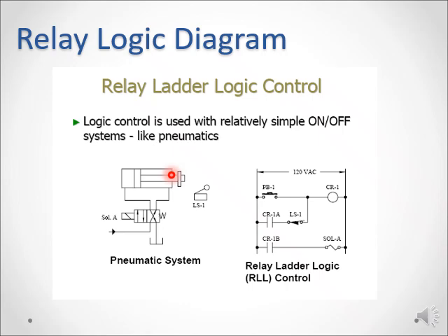What we want to do is press a PB1 switch, and the cylinder will go all the way to hit something. It will hit the limit switch at the end, and once the limit switch is hit, it will immediately come back to its original position. That is what is desired. This is called one-shot cylinder control. So let's see how it can be operated. Given the scenario, how can we achieve this solution?